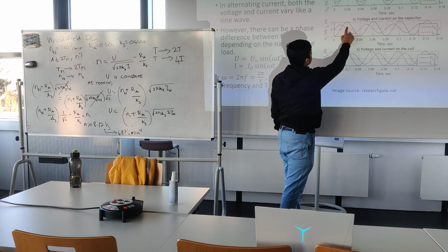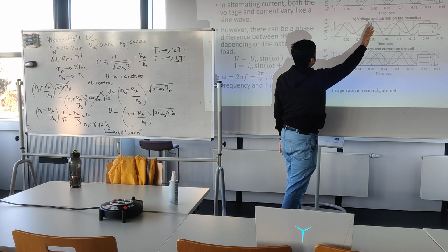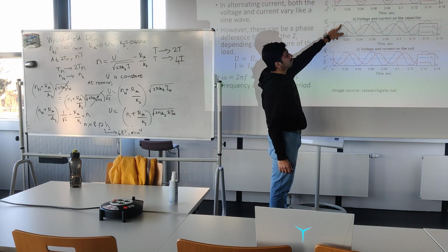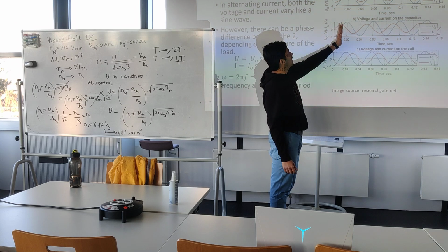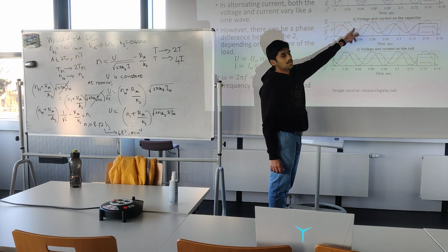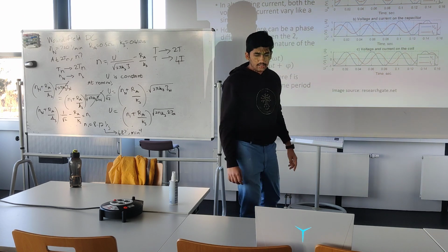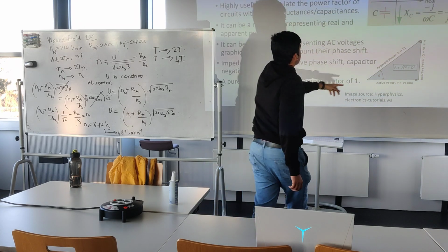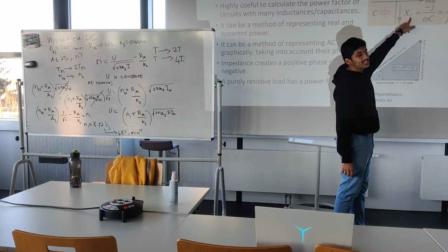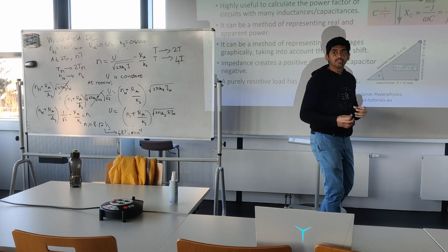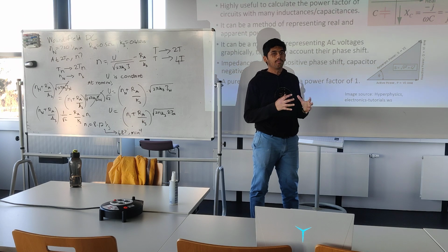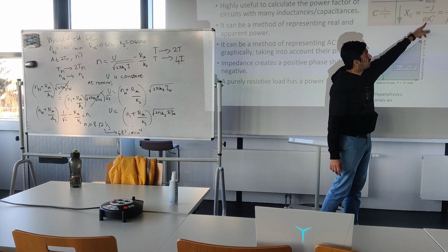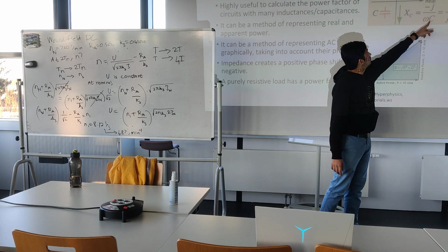But for the capacitor, the current is peaking ahead of, it's actually lagging behind because the voltage has peaked earlier, but at a later point in time the current is peaking. That's because the capacitor has a different sign. As you can see, the capacitor has a different impedance. In AC we don't use resistance, instead we use this combined term called impedance, which takes into account the effects of the frequency and the capacitance.